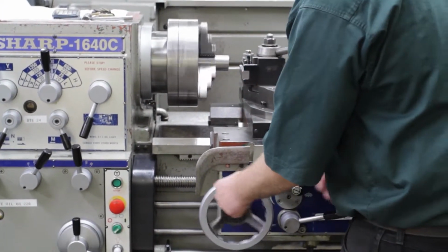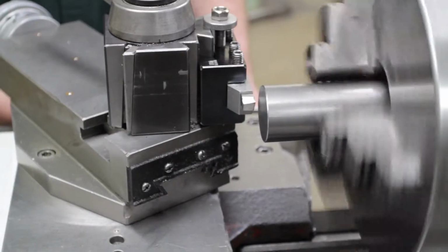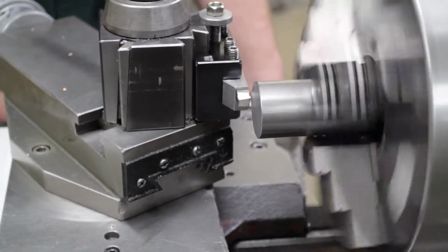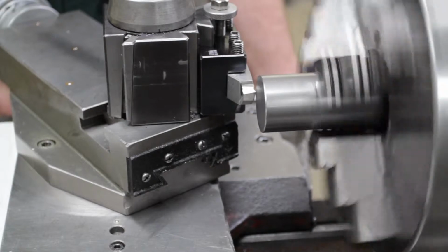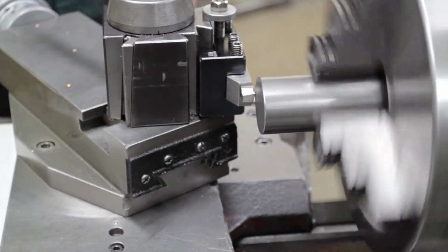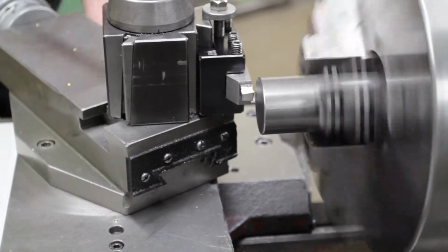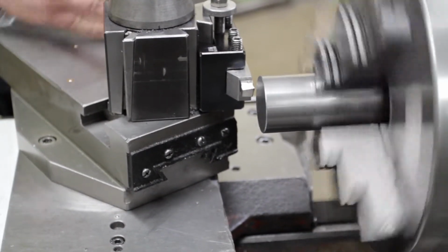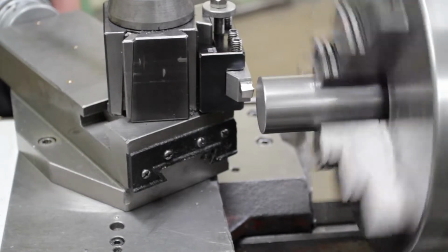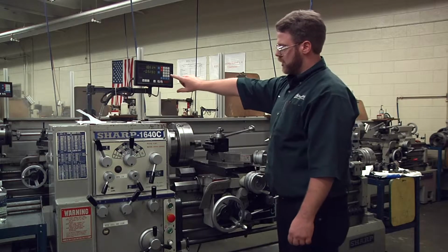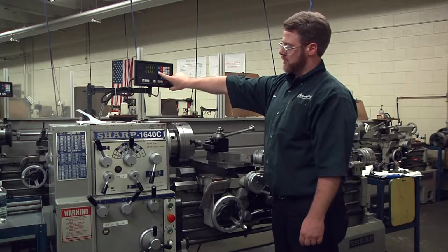And then you want to bring your tool bit close to the material. All right, so let's bring it up just until it touches the end of the material, and you'll see it scrape the end. And then you will take the X hand wheel and bring it counterclockwise. That brings the carriage back away, towards you, away from the material. And now at this point where it's touching, I'm just going to zero the Z-axis.